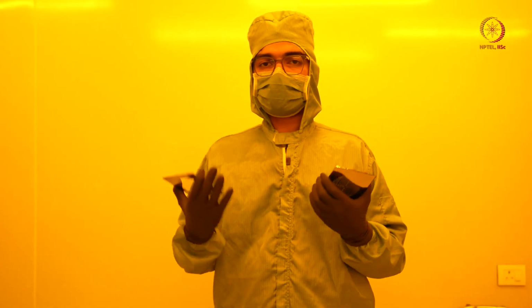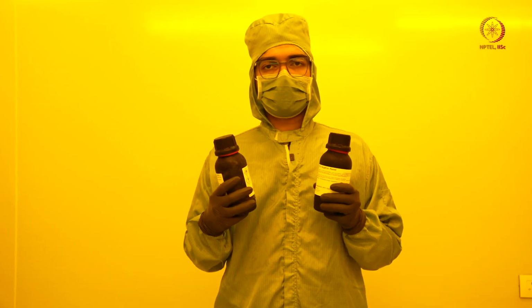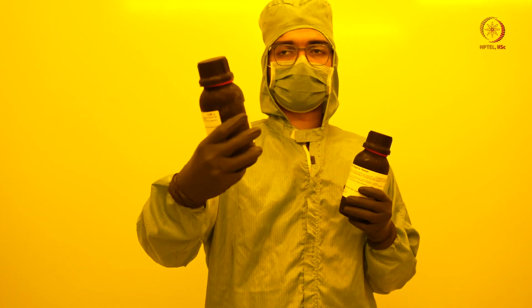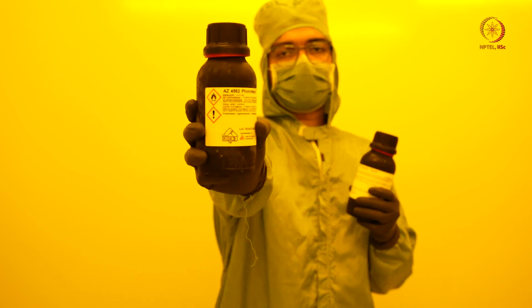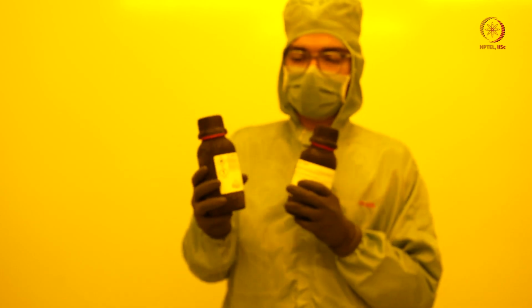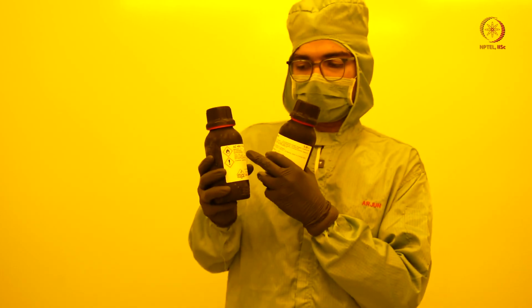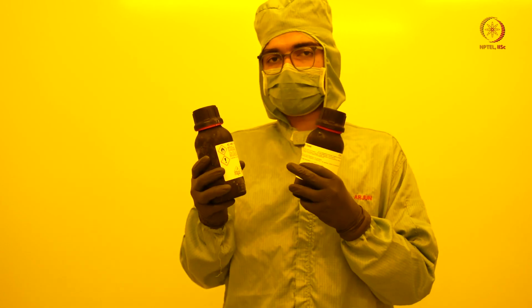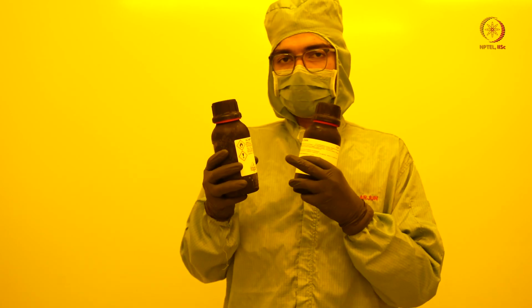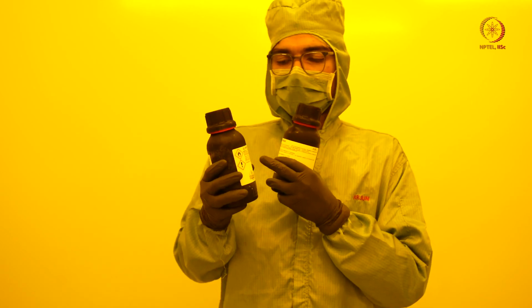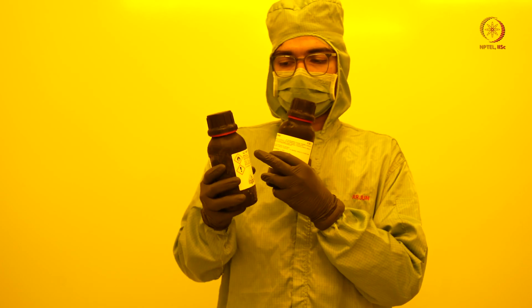Now I will show you two different types of photoresist so that you will understand what they are. I told you there are positive and negative photoresists. This is an example of a positive photoresist, which is AZ 4562. Most photoresists with a number like this, say 4562, have something associated with that number in their properties. What it means is that the coating procedure, or the spin coating procedure, that we use for this photoresist is somewhat evident from this number.